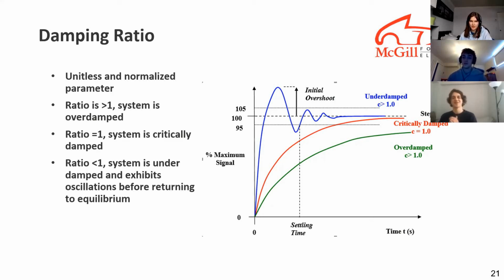Yeah, exactly. But why are we talking about damping ratio right now? Like, why am I learning about damping ratio? Well, it's an important value so that we can make sure that we choose a suitable damper and that our damper setting is correct. Because in the end, at MFE, we buy our dampers and we want to make sure that the dampers have the right damping ratio for the kinds of racing that we're going to be doing. Perfect.